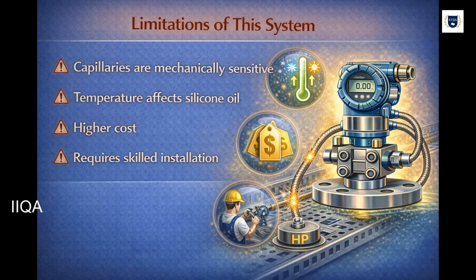What are the limitations of this system? Capillaries are mechanically sensitive. Temperature affects silicone oil. Higher cost. Requires skilled installation.